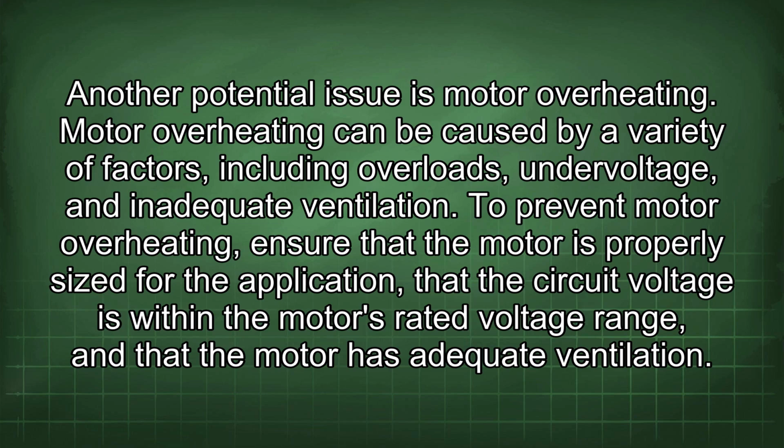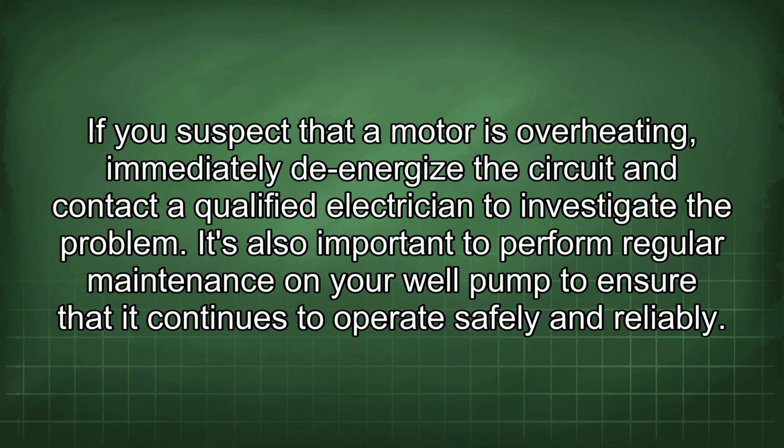Another potential issue is motor overheating. Motor overheating can be caused by a variety of factors, including overloads, undervoltage, and inadequate ventilation. To prevent motor overheating, ensure that the motor is properly sized for the application, that the circuit voltage is within the motor's rated voltage range, and that the motor has adequate ventilation. If you suspect that a motor is overheating, immediately de-energize the circuit and contact a qualified electrician to investigate the problem.